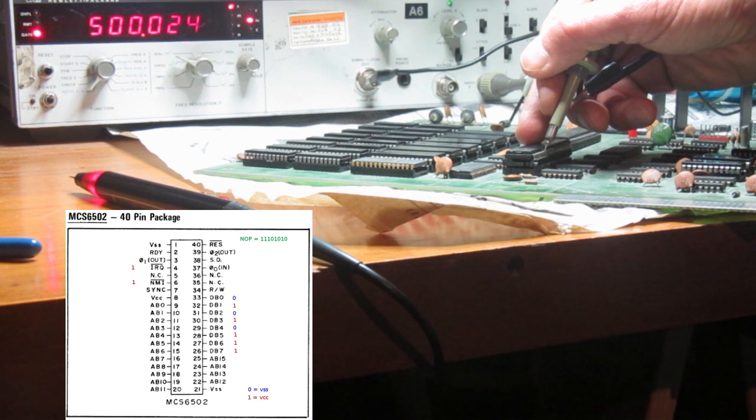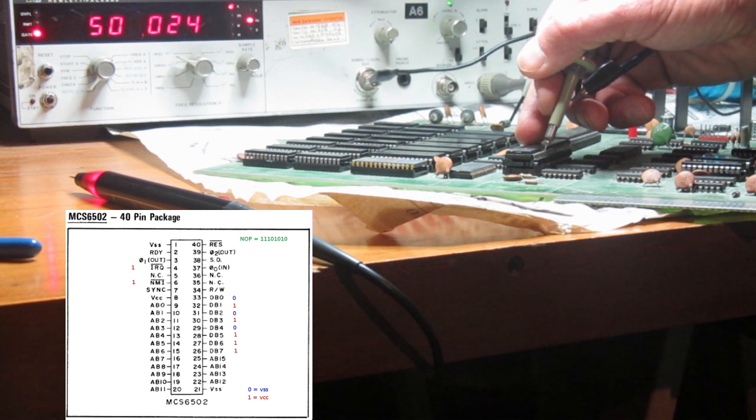And on another cycle, the CPU is executing this instruction, which means it's just wasting one cycle. So the sync pin indicates when the CPU is executing one instruction, so it's half the clock frequency, because the first half is the fetch, second half is execution.